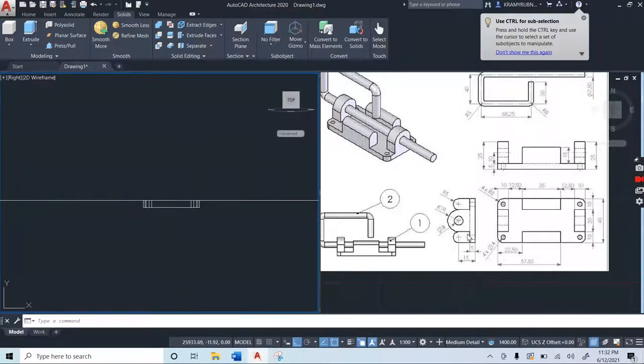Now the pieces we're now going to be drawing represents these 2 end pieces plus the center piece. The dimensions are given as 15 millimeters from the curve to the base of the base plate. Since we already have the base plate, what we are going to be doing is to draw a rectangle, or a square rather, which is going to be 10 millimeters, which is the 15 minus the 5, by 10 millimeters.